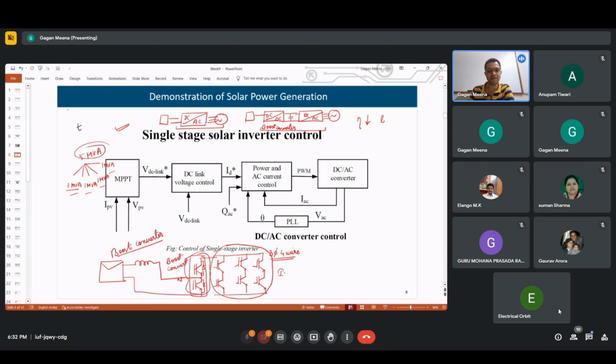Then another is dynamic pricing with automatic control. With time of use tariff, without control, we have peak and off peak pricing, so there is no control. But with dynamic pricing, we can control which electric vehicle to charge, and how much. So all these are different types of charging methodologies.